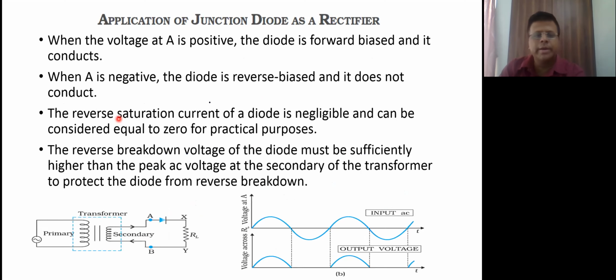Now, going ahead here, one care you have to take, of course, is that this reverse biasing should not exceed the peak reverse voltage and ensure that the diode does not go into the breakdown region, because in the reverse direction you need to take care of that. Otherwise, if the diode goes in the breakdown region, then it will no longer function like a normal diode. Very large current will start flowing through the diode. So that's one care we need to take.